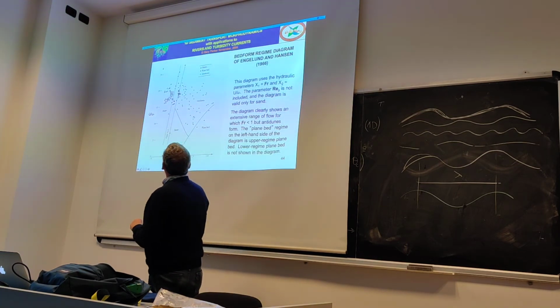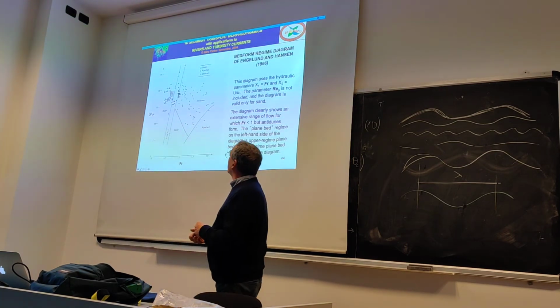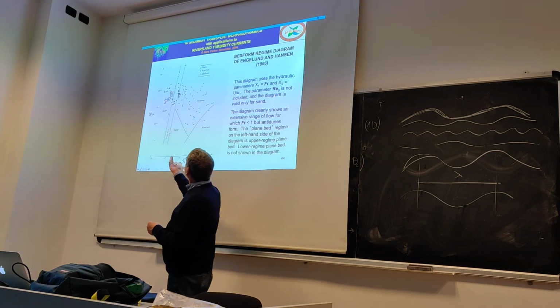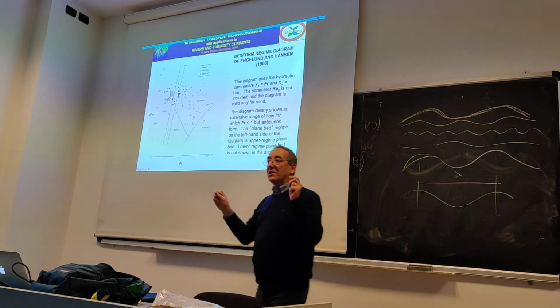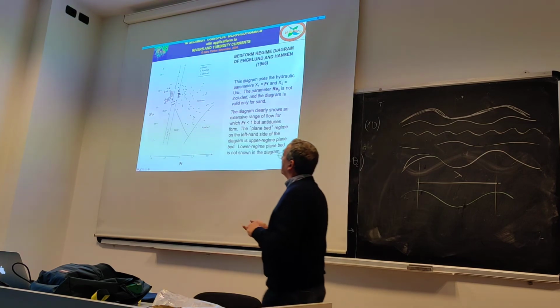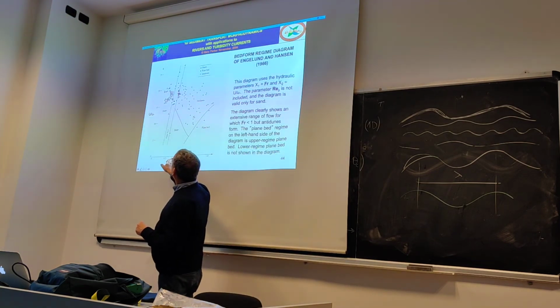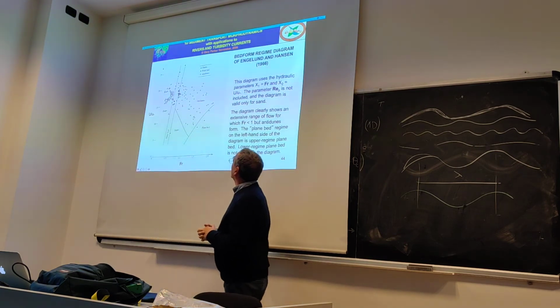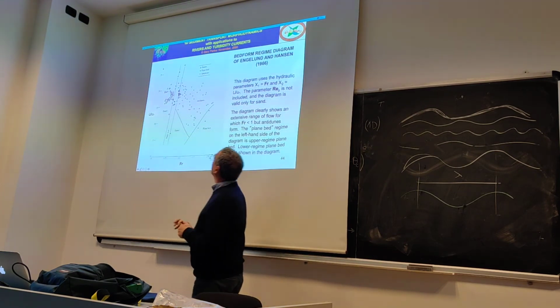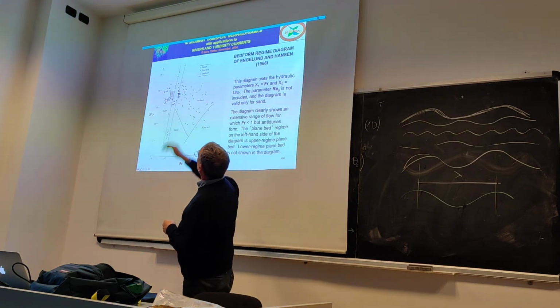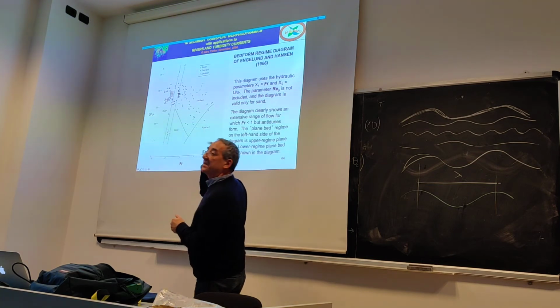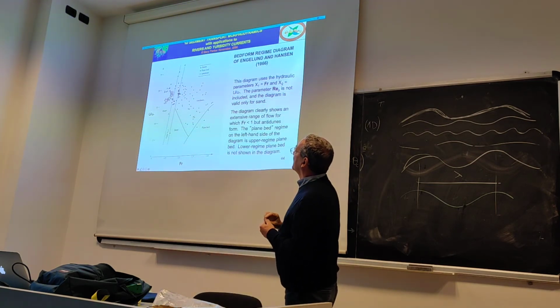And then the Froude number, a parameter which is typical of the flow. Then you see if you go up with the Froude number, if you exceed 1, you are in the realm of anti-dunes. Actually, you start to see them at about 0.8 here, and then you go up to 1.5, 20. Forget for a moment about this plate back here. Stay around 20 or around 15. Make a line on that.